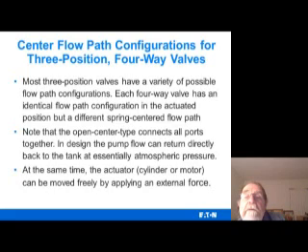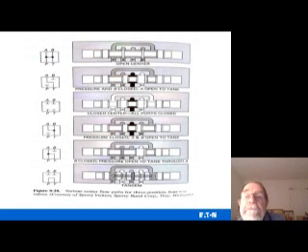Most three-position valves have a variety of possible flow path configurations. Each four-way valve has an identical flow path configuration in the actuated position, but a different spring-centered flow path. Note that the open-centered type connects all ports together. In this design, the pump flow can return directly back to the tank at essentially atmospheric pressure. At the same time, the actuator, cylinder, or motor can be moved freely by applying an external force.